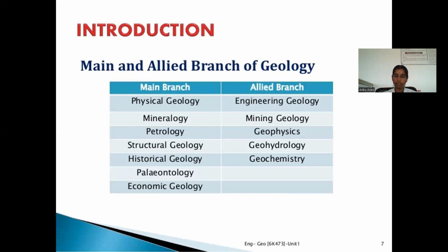Then tunnels. For a construction of tunnel, before that, we need to learn about the general topography, composition of attitude and altitude of rocks, then structural characteristics of rock like fold, fault, joint, like that, then hydrological conditions and borehole sampling.